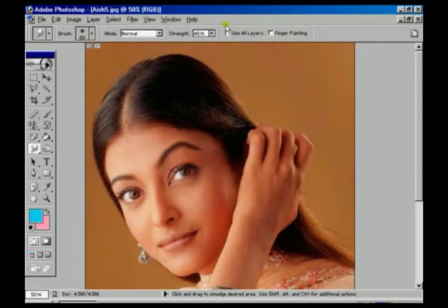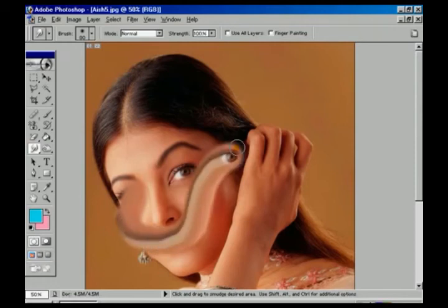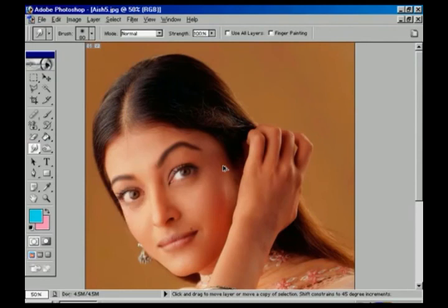When the Smudge tool's strength value is more, then it is treated as a hard Smudge tool, and we can pull one particular area from one point to another point. Now Ctrl Z for the step backward. F12 to come back to the same position. Now we are going to close that particular file.